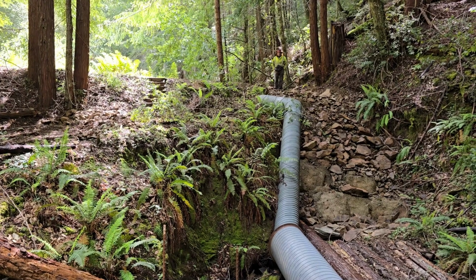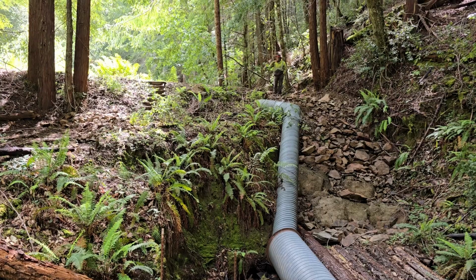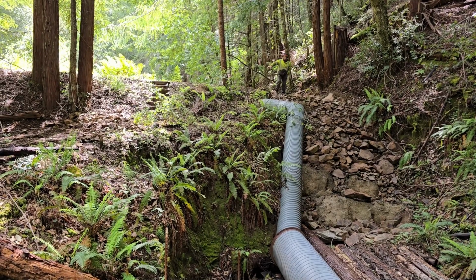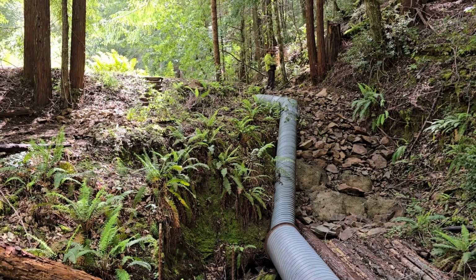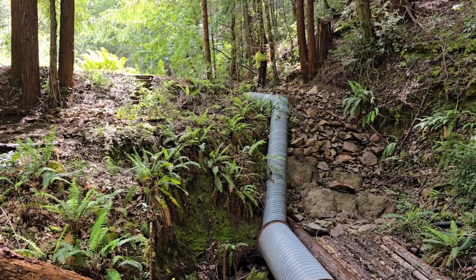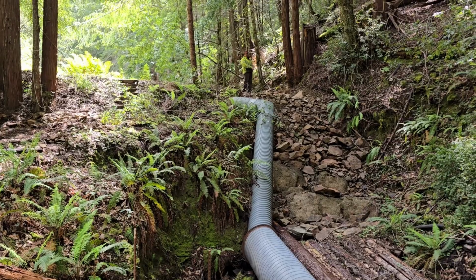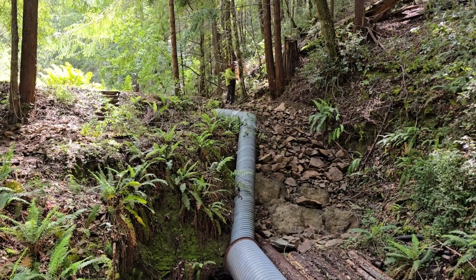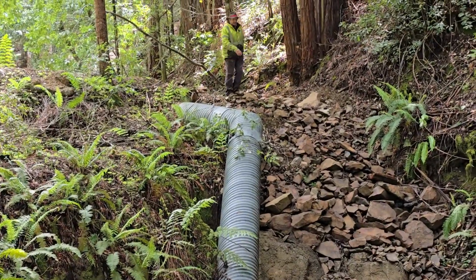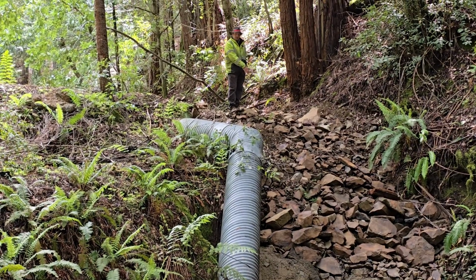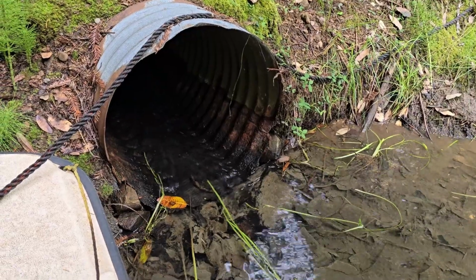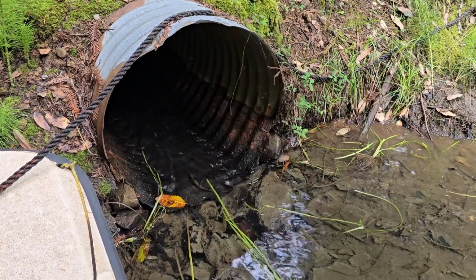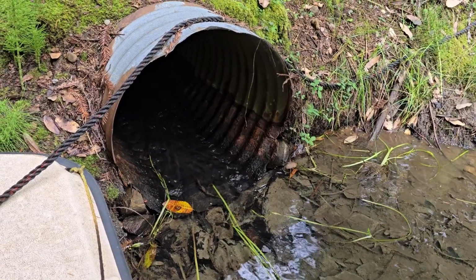You're looking at the rebuilt spillway that's no longer eroding. Large boulders were embedded into the ground at the base of the spillway to control the head cut. The overflow pipe was extended so there would be no erosion taking place at the outlet end of the culvert. The spillway was made wider and then armored with angular rock to control erosion. The galvanized steel overflow pipe will carry the normal flow over the dam without causing erosion.